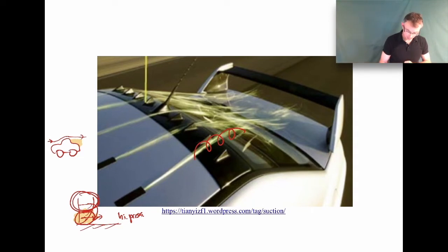But if you have these vortex generators, the flow has more momentum to it, and it can actually follow the contour a little bit better because you put more momentum into the boundary layer. We're going to talk about that topic in detail in a couple of lectures. I just wanted to give you a little preview here, and it's a neat picture related to boundary layers. By putting these vortex generators on here, you can actually reduce the amount of drag acting on the car and improve gas mileage and such. So it's kind of a neat idea.